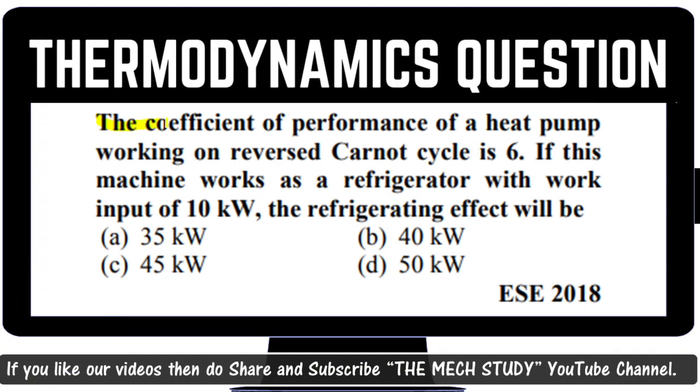The coefficient of performance, COP, of a heat pump, remember the word heat pump, working on a reversible Carnot cycle is 6. If this machine works as a refrigerator, reversing the cycle, with work input of 10 kilowatt, then what will the refrigerating effect be? If you remember the second law of thermodynamics, they have derived the formula for the COP of a heat pump as well as the COP of a refrigerator. If you know the relation between them, then you can solve this question, because this question was asked in ESE 2018. If you do not have an idea, then definitely you will mark a wrong answer.